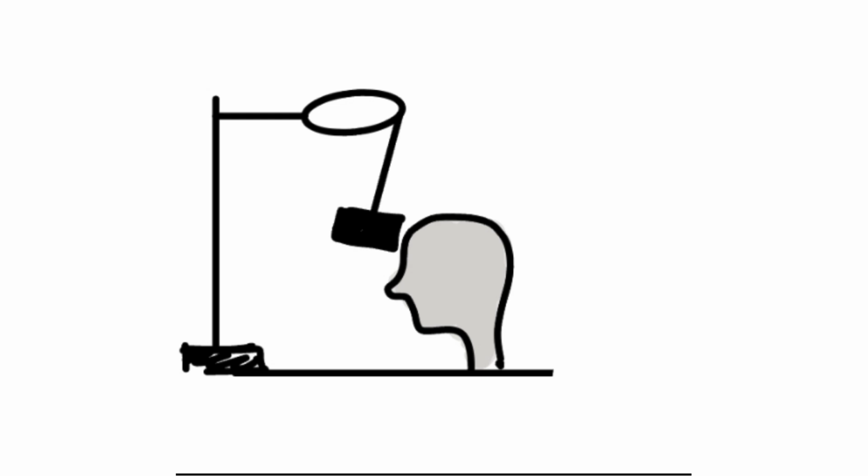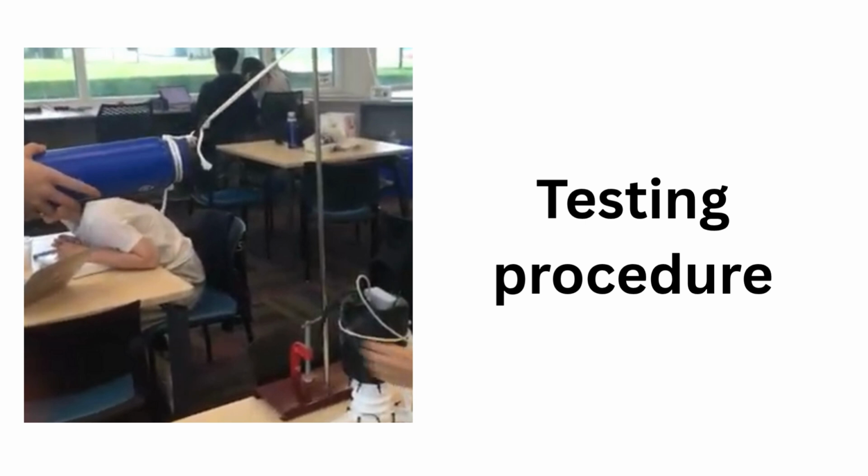So, how is it being tested? Well, our test rig consists of a water bottle that's approximately 760 grams mounted to a retort stand to produce a pendulum. It will be released at an angle of approximately 60 degrees to simulate a low-impact strike. The idea is that the potential energy from the height and mass will suffice as a low, constant, controlled impact force. So the physics behind our test rig comes down to our instrument's recording method.